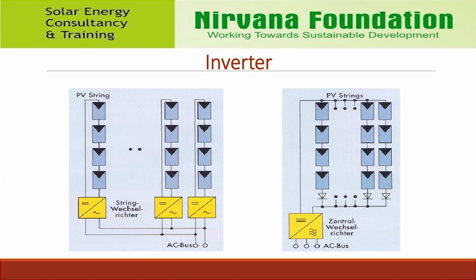The larger the scale, the greater the savings. Since the upfront cost of string inverters is greater and the logistics of installing so many of them are more complicated on projects size 10 MW and larger, central inverters will likely continue to win on very large projects, especially at a higher voltage.